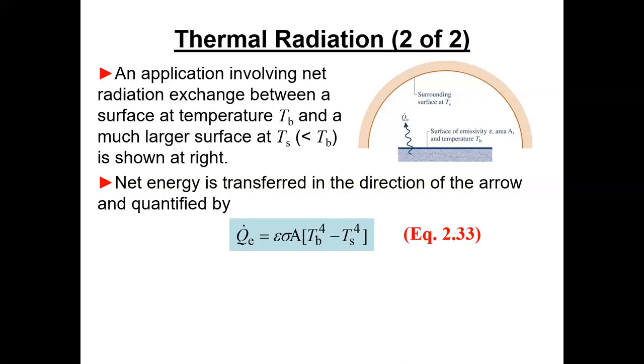Well, see, they conveniently put this hemisphere over it. So the view factor, from the slab to the surroundings, is 1, because that's all the top of that slab that's doing the radiation can see. That whole thing is laying over the top of it.